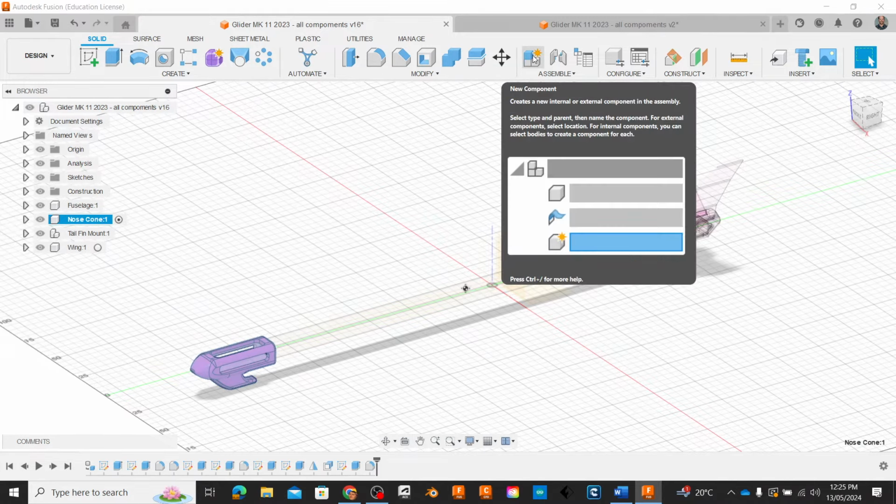Right, and you'll see this in your model tree as well. If you activate the wing profile, so I might try and move all these construction planes that I've just made to the wing profile. There we go. So I misplaced them. I just put them in the general model tree. But what I've done there is I've control selected the planes that I wanted to put into the wing component, and I've just dragged and dropped them, and now you'll see them here. That's good, that worked well.